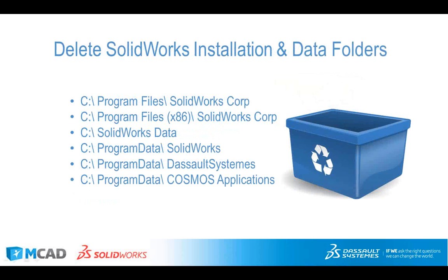After this is done, I double check just to make sure that the installation folders are deleted. Sometimes I've seen it might say SolidWorks and then parentheses 2, and that might have been from a previous install where instead of overwriting a folder, it made a new folder. So at this point, I know I've uninstalled the program, so this is when I scan my C drive and see if there are folders still existing that are definitely unneeded, because SolidWorks, all add-ins and all previous releases are gone from my system. So those are just some general locations to check.